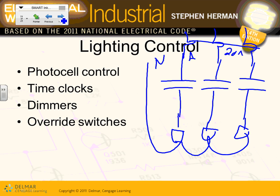It's phase A, phase B, phase C. That's typically how you wire a lot of them. I'm going to have 10 here, 10 here, 10 here, and these are big lights. So 10 in each, or it could be 5 in each if they're 20 amps. And these wires here, I'm going to make them number 6 conductor. Everybody knows why number 6 conductors? Because they're going longer distances.